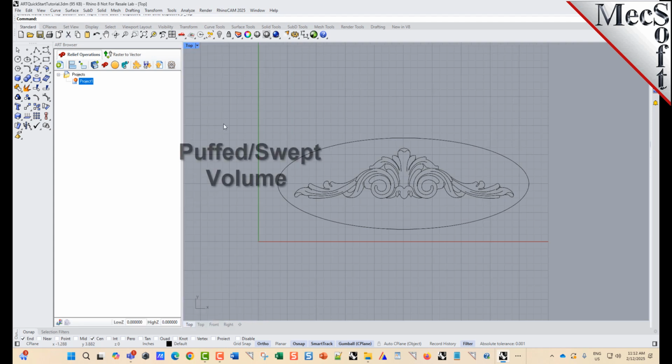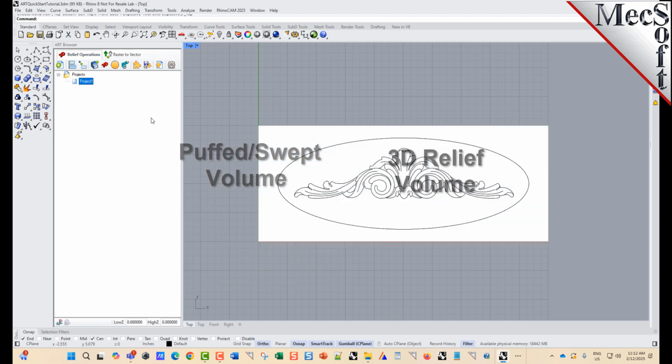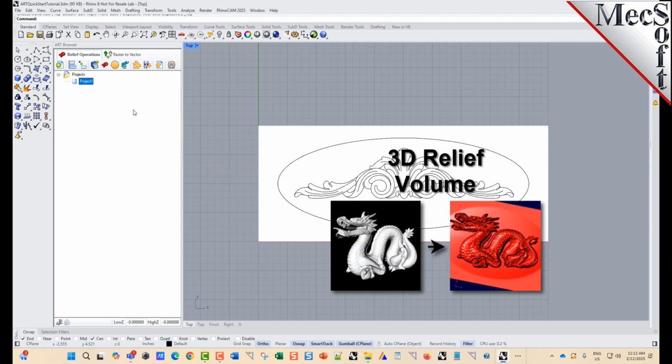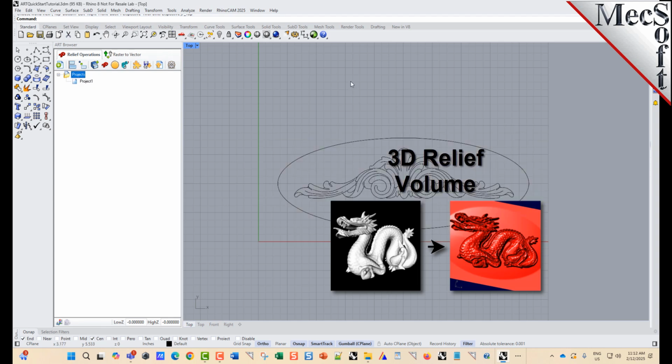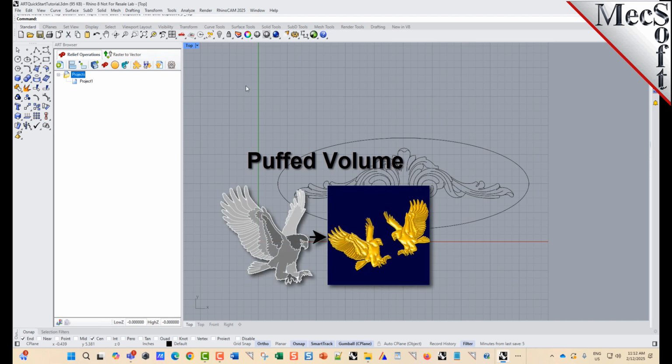accessible. RhinoCAM's ART module, also referred to as RhinoART, is used to convert artwork into geometry, suitable for machining or 3D printing. You can create 3D reliefs and wireframe geometry from various picture file formats and a variety of bitmaps and operations to create different shapes.